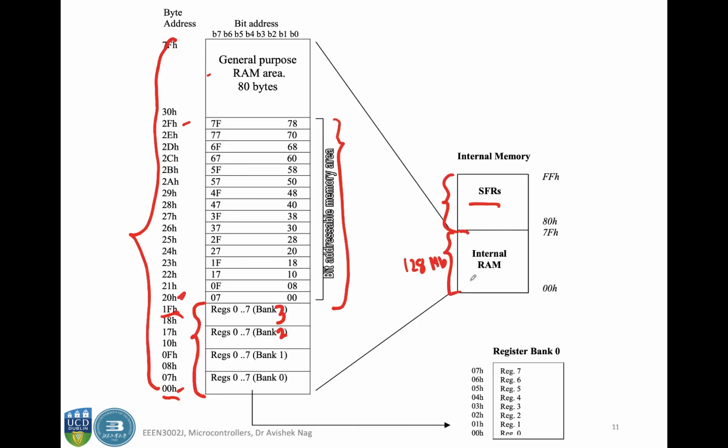So let me go back and explain that to you. We were setting the bit 25H, and then we were clearing that bit also. So let's see what is 25H. When you are using set and clear, this means you are actually operating in the bit addressable area, because these are operating on individual bits. So let's say 25H. You have to count from here.